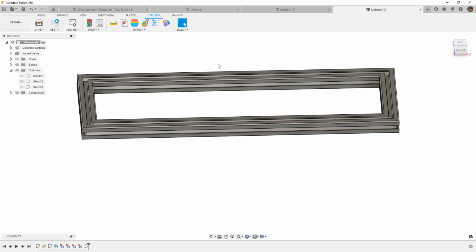But at this stage, we know quite a bit about API, at least enough to make us dangerous. So we can do things like create user parameters. We can get some input from the user. We know how to create new sketches, access current editing sketches or sketches that are currently being edited. And we know how to create things like lines, arcs, circles, and rectangles. So from here, the next logical step is either to learn about dimensions and constraints on a sketch or how to automatically turn that sketch into a feature.